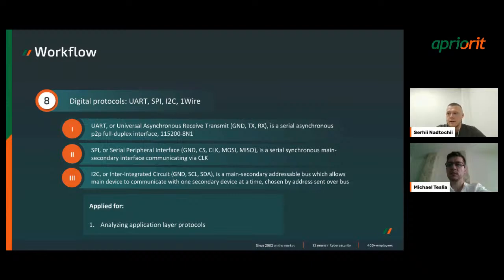And for example, it can also be some custom interfaces and protocols, like some parallel interface, where you can just connect 8 lines between two microcontrollers and you now have a parallel interface which will transfer 8 bits of information for one clock of the CPU.